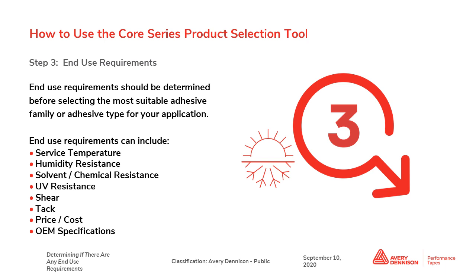So again, step 3, this is how do these parts stay stuck, right? There's going to be a variety of factors that affect the adhesive performance and making sure the part stays bonded. One of the main considerations is service temperature. This is not the temperature at application, but the temperature that the end-use part might be exposed to. For example, a car is assembled, there's a polyurethane die-cut part inside the car. Maybe this car is exposed to the heat wave in Los Angeles last weekend where you're at very high temperatures. That would be the service temperature.